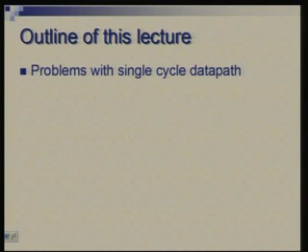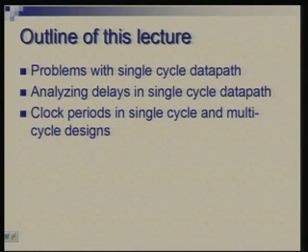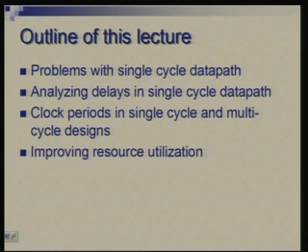This is the overall lecture plan, and today we will start by reobserving those problems which are related to single cycle data path. We will look at how we analyze the delays and what difficulty was noticed. We will see how the clock period can be improved, how the clock could be speeded up by using multi-cycle design. We will also look at this as a way of improving resource utilization.